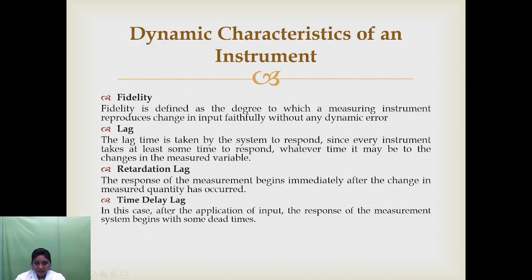In retardation lag, the response of the measurement begins immediately after the change in the measured quantity has occurred. So in this case, the response of the system begins immediately after a change in the variable has occurred, though it takes some time to reach the final value.